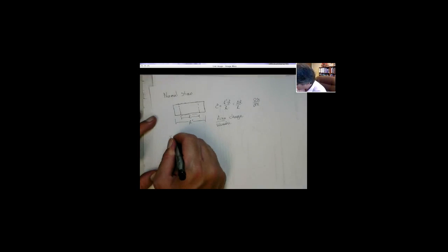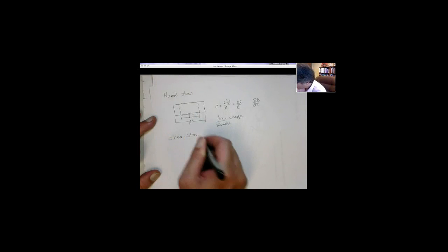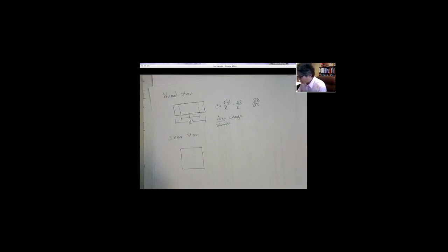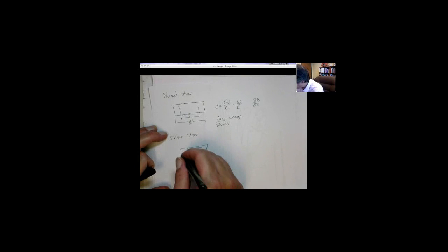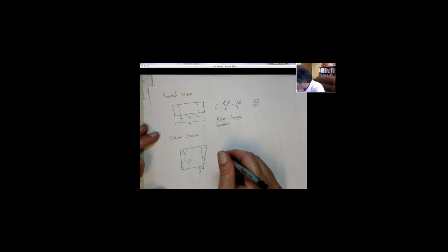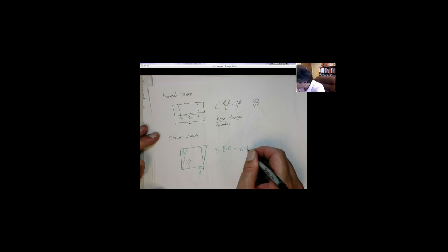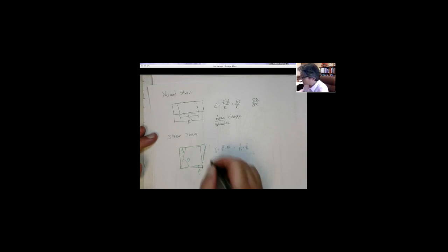The other type is shearing. And this is the one. We have a body originally like this. It will deform and shear to some angles. There you go. And here's theta 1, and here's theta 2. But the shear strain is how much this included angle is changed off of 90, right? So the shear strain is pi on 2 minus theta, but you can see that that's the same as phi 1 plus phi 2. Okay? And again, you can remember these equations, but I'm not a big fan of memorizing equations as much as I think this is a concept.